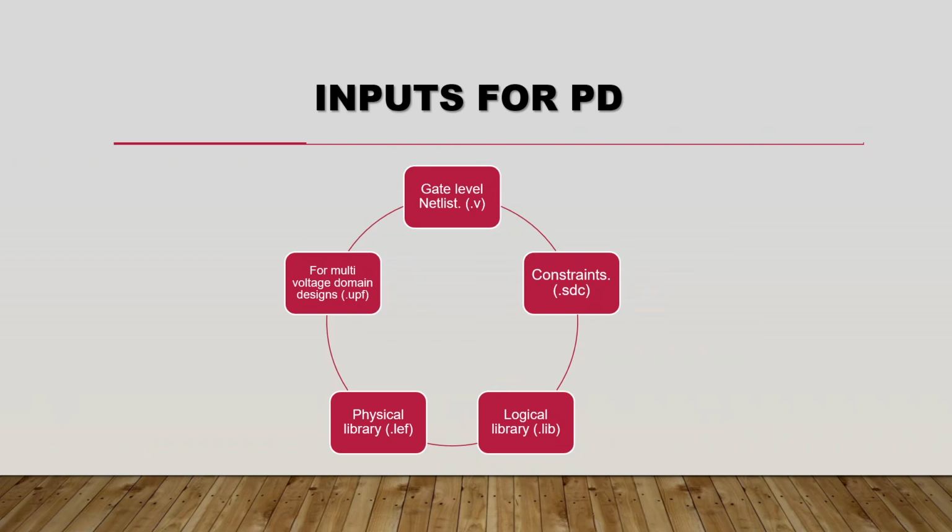As I told you, what are the inputs for PD engineers? The front end engineers will synthesize their code. In synthesis, they will generate the gate level netlist. So the gate level netlist is the input for PD engineers, that is the dot V file.